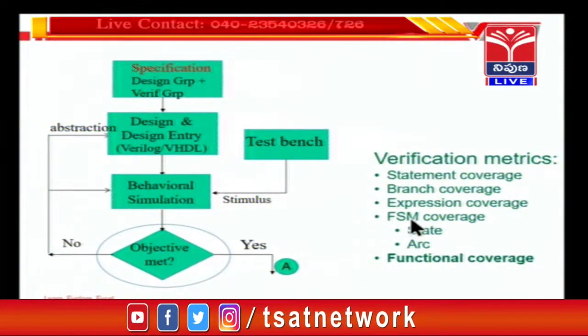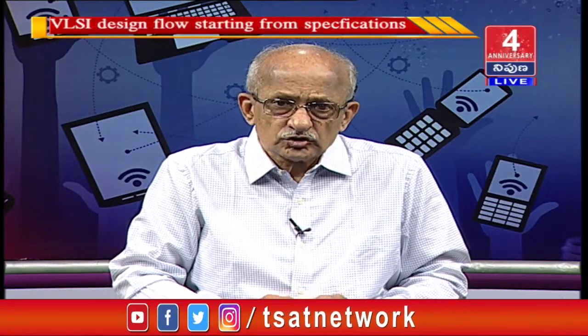What is functional coverage? Functional coverage means that the verification team lists out all possible scenarios with which the design can be verified or tested. Based on the specification, they come out with a complete list of scenarios.